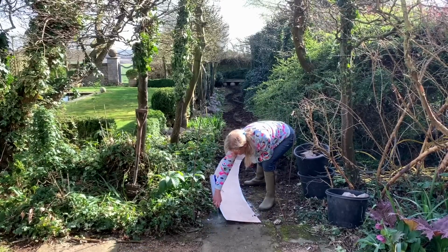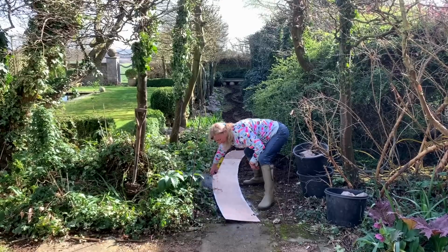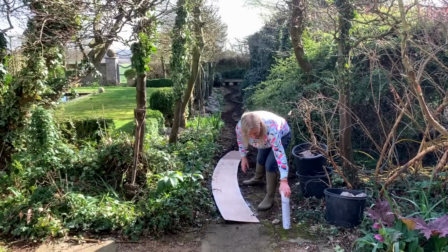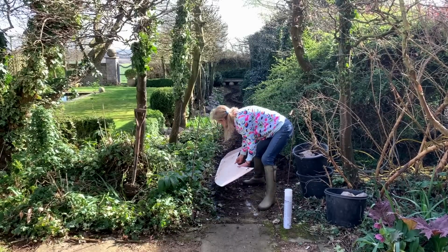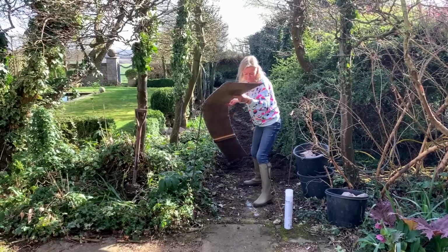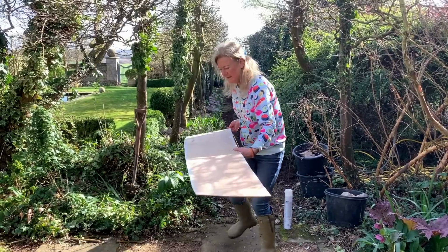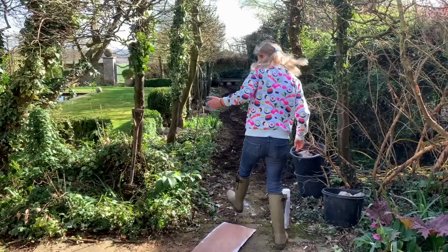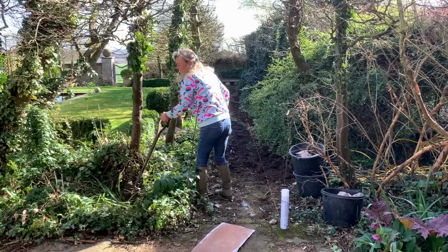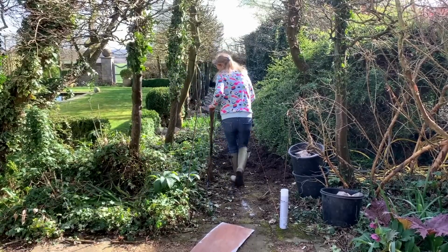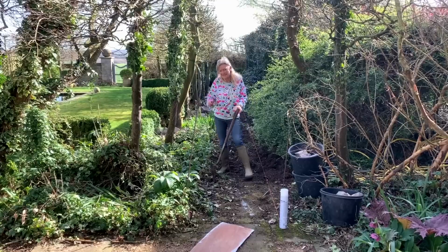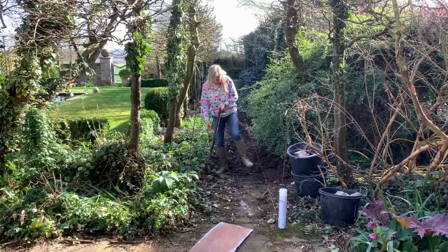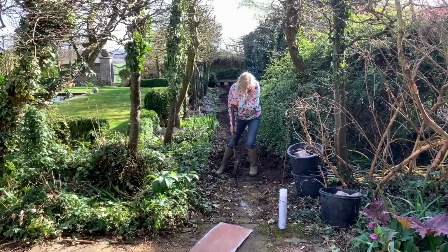Now, I've actually done it slightly differently. When I've done the whole thing, I remove this, and then I've just dug it out to that width, which you can see there. I'm digging it to a depth of just the sets and about 60 mil of mortar, so about 100 mil deep, something like that. And because I've glyphosated off the grass, it's quite easy.